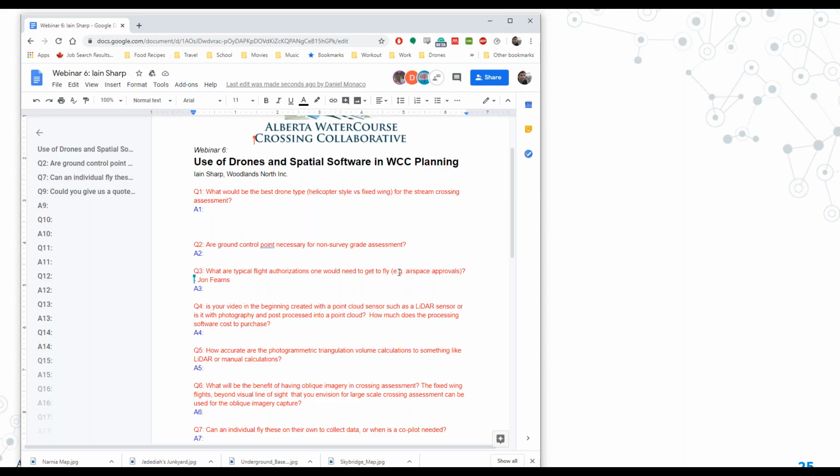All right, great, thanks. The next question is, what are the typical flight authorizations one would need to fly, for example, airspace approvals? Typically nowadays, a lot of the drone software, especially the flight planners, actually have the airspaces uploaded into the imagery. So using the GPS coordinates of the drone, it knows what airspace it is in.